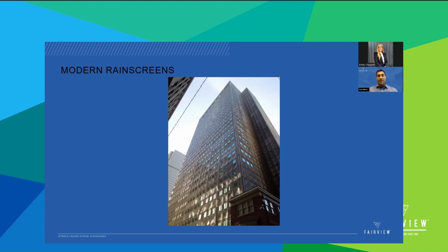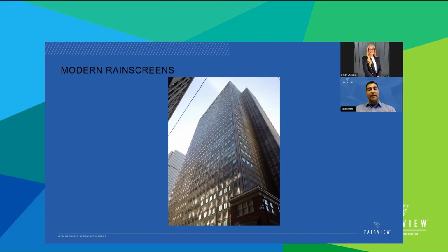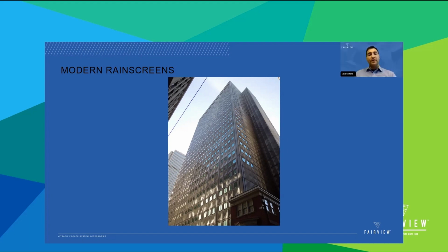The double layer principle of construction of this type of wall assembly concept was born, with an outer surface to control, but not completely prevent, the rain and moisture penetration. What happens is that the interior element of the wall assembly provides the insulation value, limits the air leakage, protecting the building, and prevents vapor penetration into the surface of the building.